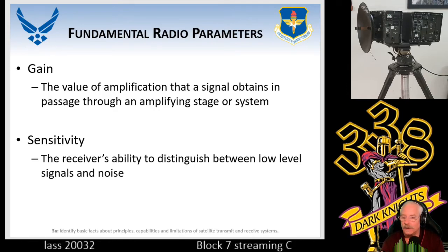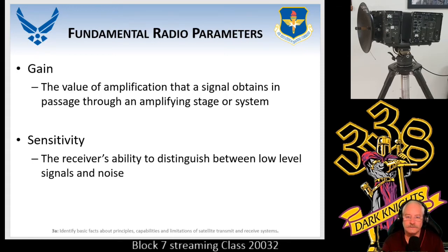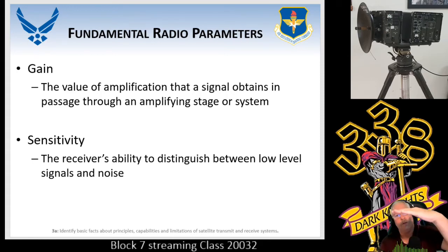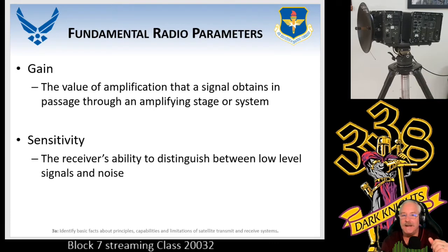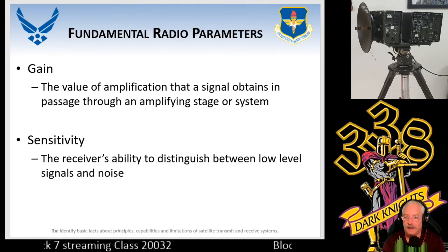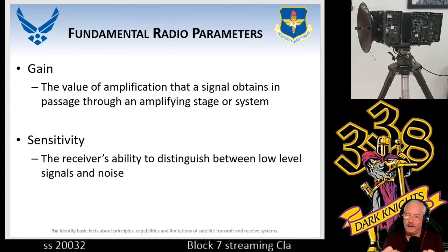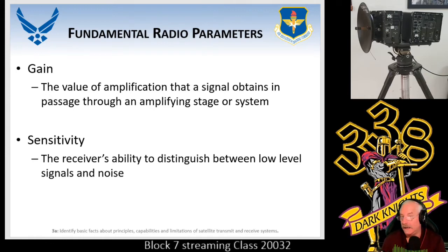Well, normally you have a filter on it to clean out that one signal, normally that 1 kHz tone when you set it up. And all you're going to hear is noise. The threshold of where the signal plus noise is and where the actual noise floor is has to be at least a minimum of a 10 dB drop or it fails. Better than a 10 dB drop, in other words 11, 12, 13, 14, is good. So that's what sensitivity is checking, is how able this receiver is able to pull the signal out of the noise floor and make it legible.